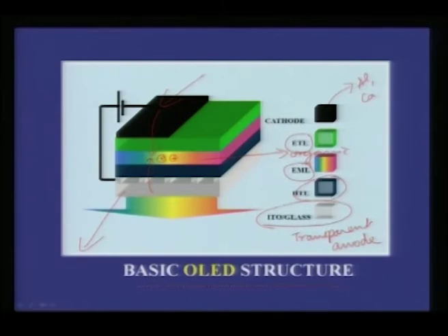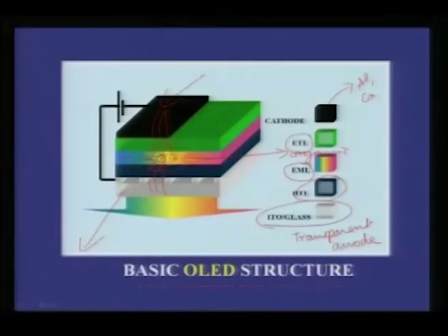It is not a simple 5-layer structure which forms an OLED, because the number of electrons that keep coming here and the number of holes going towards the emissive layer both need to be controlled. Not only that, the speed with which these electrons and holes reach the emissive layer, which we call mobility, also matters. So, a proper recombination has to occur in this layer.